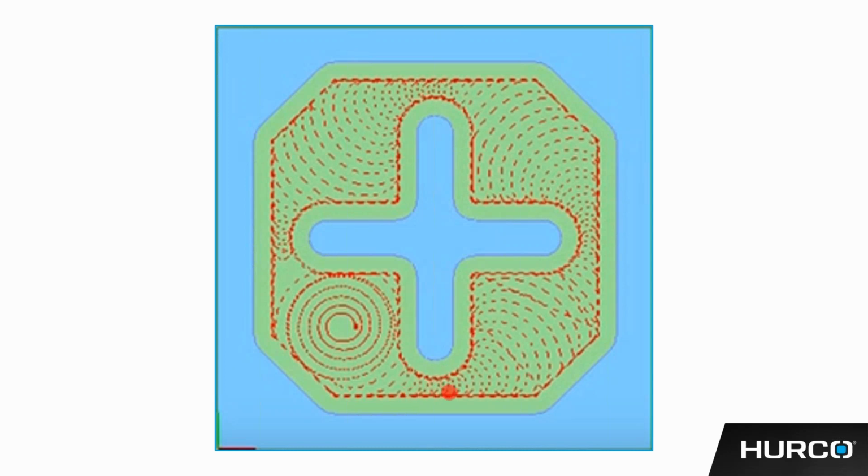The one-way method is a little bit more common. You see that used a little bit more, again, I believe just because of the always climb cutting. But typically when you see these types of tool paths, you'll notice a little arc move like that there, and then just a straight line move to start your next cut. That transition move between where it stopped the cut and starts the next cut, it will lift up a little bit in Z as well, so it's not dragging that tool right across your part.